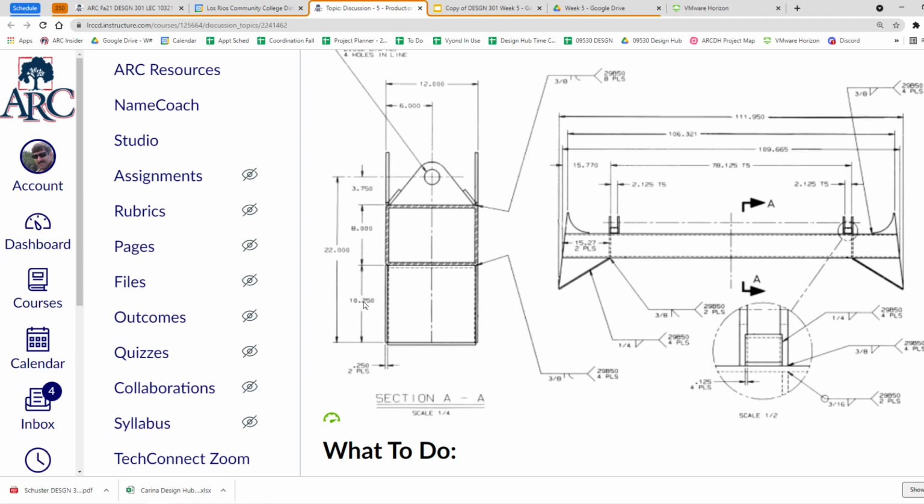So I would suspect that mostly you'll see those as 2 decimal places at the most, or fractional in most cases. Now, I got to admit, I did some weld prep for the exhaust of the Space Shuttle engine on 4-inch tubing, Inconel, 10,000ths of an inch wall, and they wanted a J prep with a 5,000ths land.